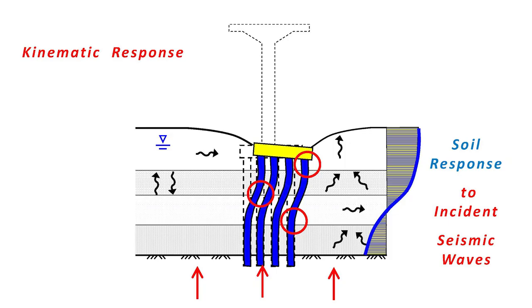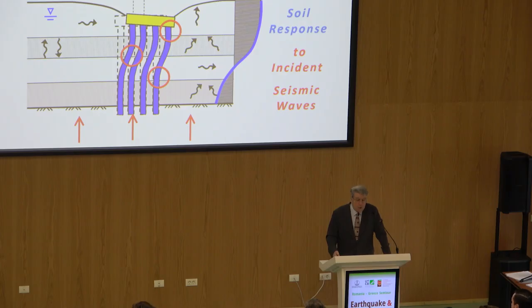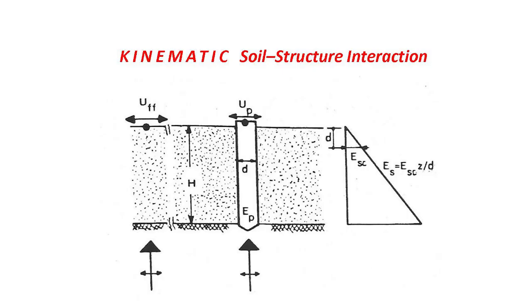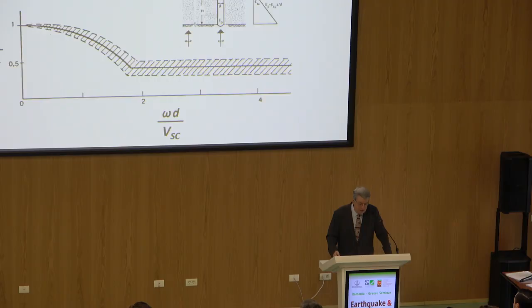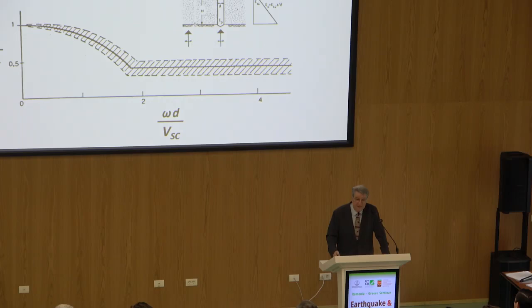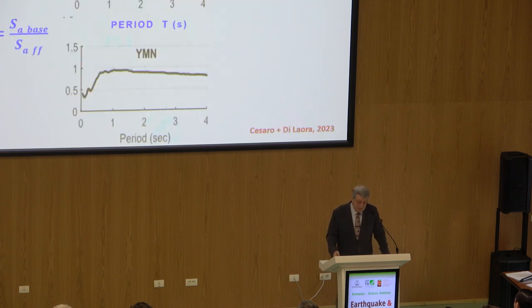Okay, now, how about piles? Now, piles, of course, they will modify the free field motion. They cannot follow the detailed motion of the ground unless the period is very large and the wavelength is very large. And I have here an example from some early studies that I did for an inhomogeneous soil and a pile, and of course the motion at the top of the pile follows more or less the initial curve that I saw before with this simple idea of averaging the motion, which convinces the students at least that this is what is happening. And all right, so this is the story.